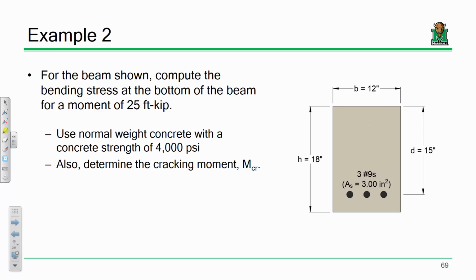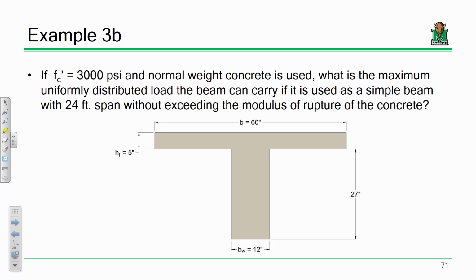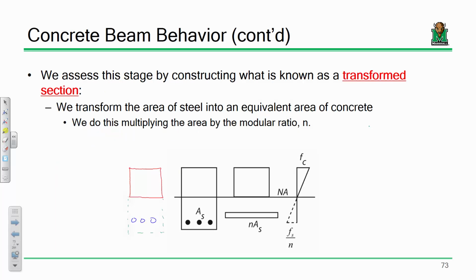Yes, sir. Yes. Because, yeah, we're replacing it with an equivalent lump of concrete, but we're talking about that theoretically. Do you see what I mean? It's not like I'm going in there with a jackhammer and actually replacing that steel with concrete. I'm saying I'm replacing this with an equivalent numerical value that has an equivalent stiffness. That's all I'm saying. This is just an analytical technique. Does that make sense? Okay.